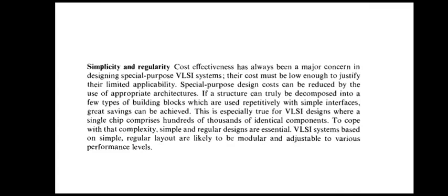Simplicity and regularity of VLSI computation. Cost effectiveness has always been a major concern in designing special purpose VLSI systems. Their cost must be low to justify their limited applicability. The cost can be reduced by the use of appropriate architecture. If a structure can truly be decomposed into a few types of building blocks, the cost can be reduced. This is especially true for VLSI design, where a single chip comprises hundreds of thousands of identical components. To cope with the complexity, simple and regular design are essential. Therefore, VLSI systems are based on simple regular layout.